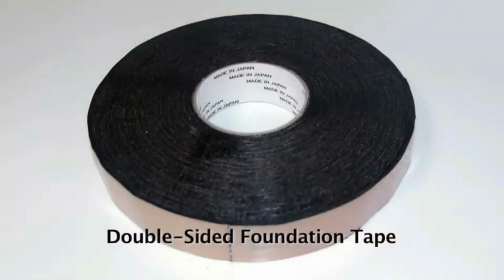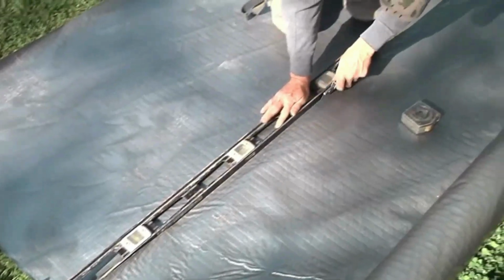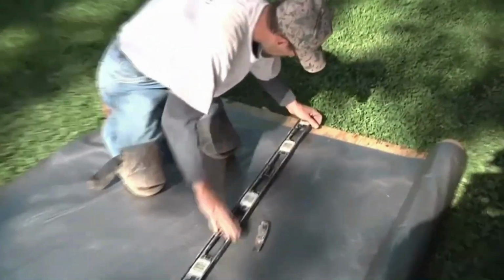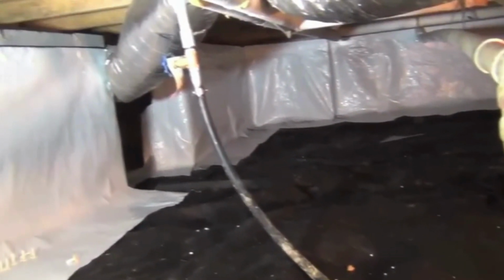Our next step involves using double-sided tape. This involves adhering the tape about 4 inches below the top of the block foundation walls and the piers throughout the crawl space. At this point, we're going to cut our pre-measured sections of vapor barrier to take down into the crawl space. Make sure to cut these outside because space is usually limited underneath of the home.